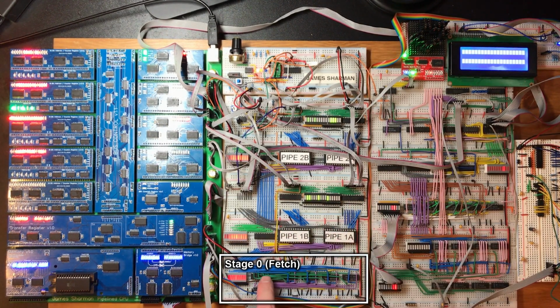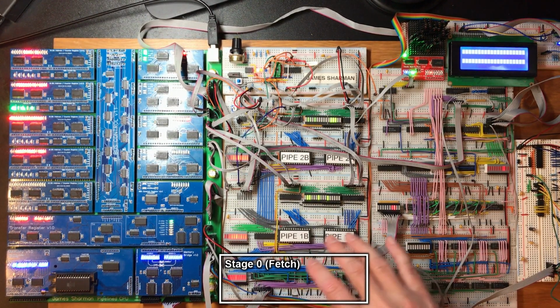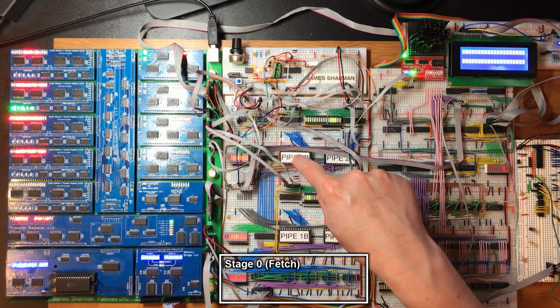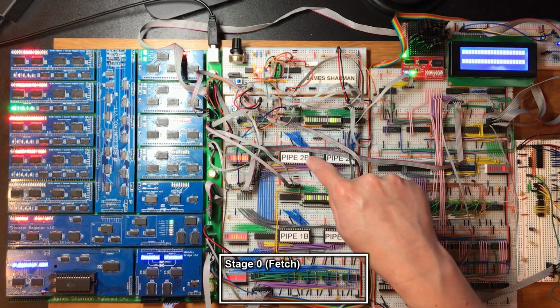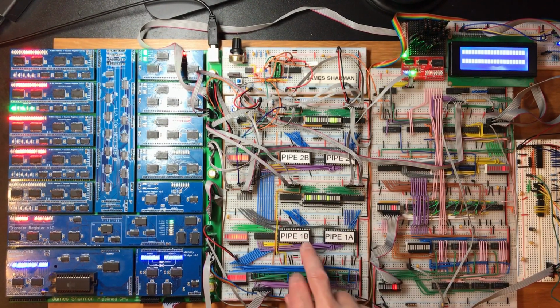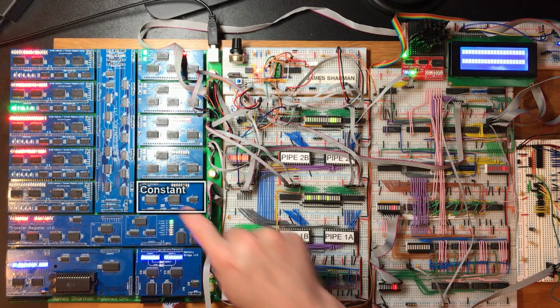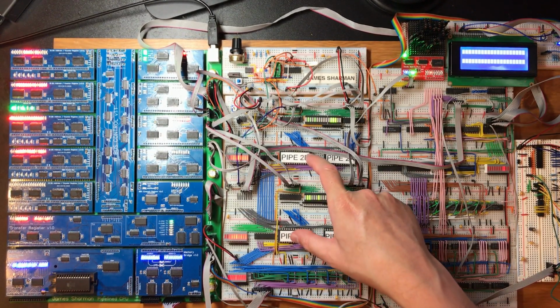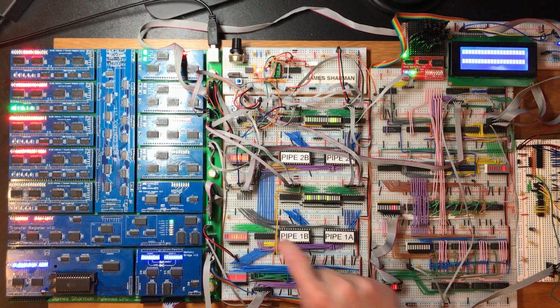In video 72, the fetch unit gained the capability of handling an instruction sequence that was previously invalid. So you've got two pipeline stages, and in pipeline stage 2, regular memory access is mediated. And in pipeline stage 1, it has the option of reading in an extra byte of data from the instruction stream to handle immediate constants. But if you have both of those executing at the same time, it doesn't work. The immediate doesn't get read.